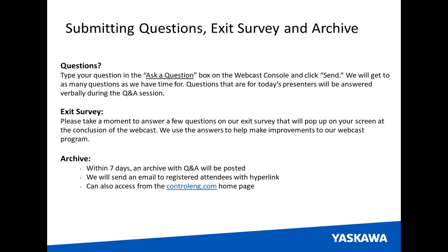Another question: can you save the parameter set in the app to quickly program multiple VFDs the same way? Yes, you can. And again, this varies by the manufacturer's app. So we could save multiple backups and restore that parameter set to the same series of drive products today.